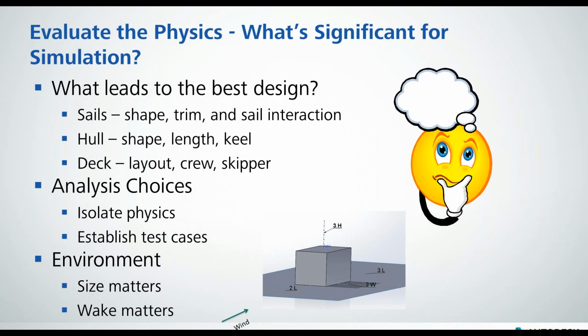When I establish my test cases, then I also need to think about the environment. Now this is kind of particular to external flows. For the environment, we're going to model the air. We're putting the boat in a box of air so that we can simulate the environment. It's kind of reverse thinking, you know, it's like, oh, I'm building a sailboat. Why would I care about the air? Well, that's what's flowing. So the size matters.